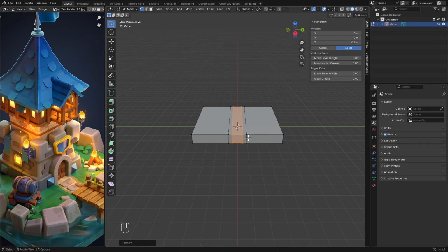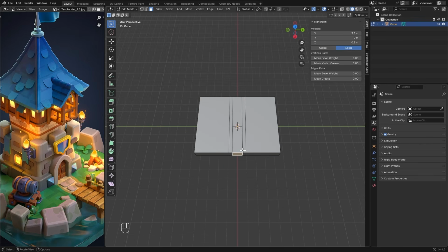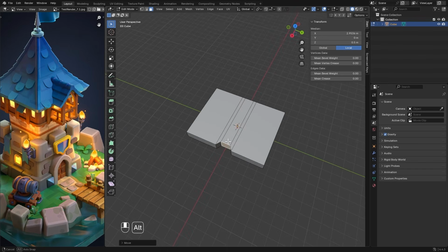Now, we're going to push one of these central faces back along the X-axis to create the indentation we need. Blender has 3 geometry selection modes: Vertex Select, Edge Select, and Face Select. We need Face Select right now. Turn it on, click on this side face to select it, press G, then X, and push it inward. Perfect, we've got the cutout for our pier.